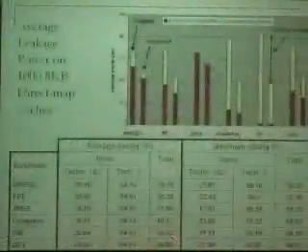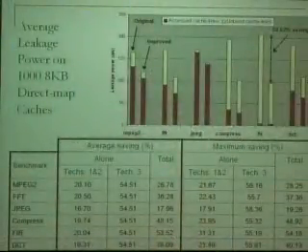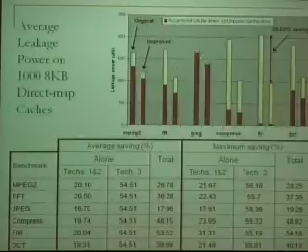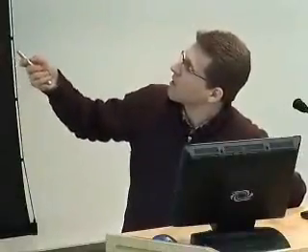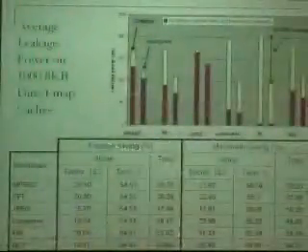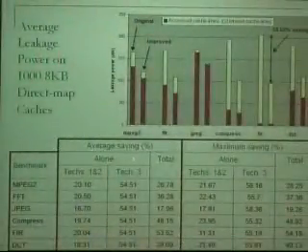Okay, so here as you see, in case of, for example, JPEG, the number of unused cache cells is very low, so you do not get as much leakage reduction as you get on FIR. FIR is a very small benchmark, so you get lots of power saving here using cache initialization. Here you see the average saving results for techniques 1 and 2. Technique 1 was instruction rescheduling, 2 is register renaming.